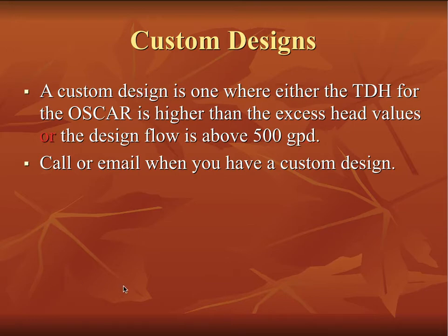A custom design also happens if we have a design flow over 500 gallons per day. Now, if the design flow is just above 500 gallons or is just above our excess head, then chances are the solutions will be rather simple, whether it's just upsizing the pipe from that 1-inch Schedule 40 PVC to 1.25 inches. But it is important that you reach out to us because it could involve multiple pumps, it could involve a new headworks, or a number of other things.